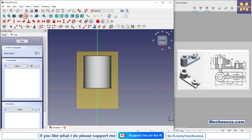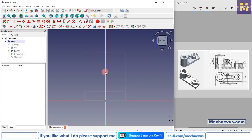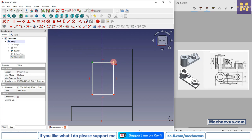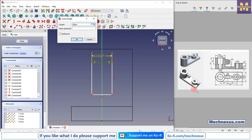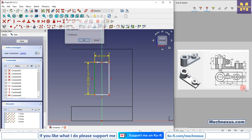So I will switch to the wireframe so that I will have the transparent view of my model. And now I will create a rectangle, and I will make this symmetric with the symmetric constraint, and I will deactivate. Now I will provide the dimension to this line which is 10 mm, and this is the R10, so the diameter will be 20, so the vertical dimension will be 20.